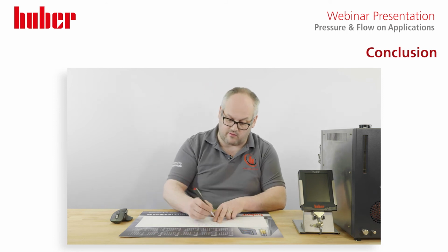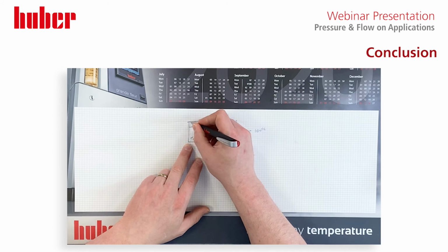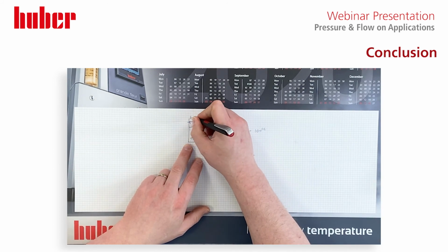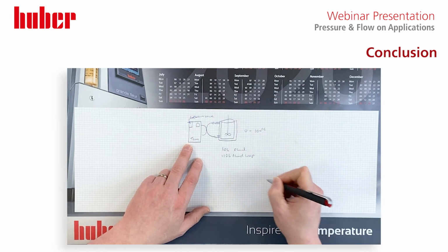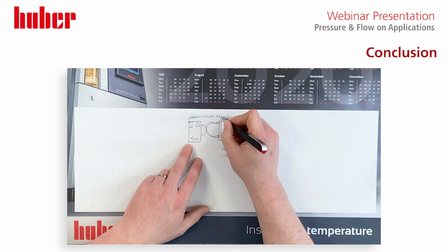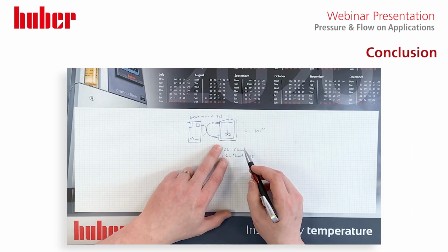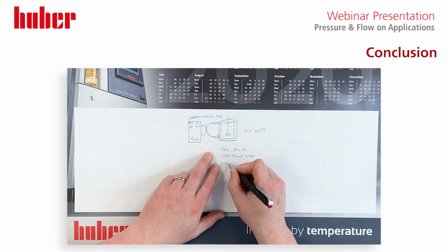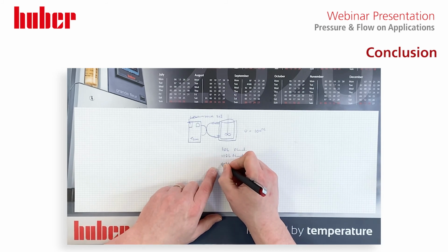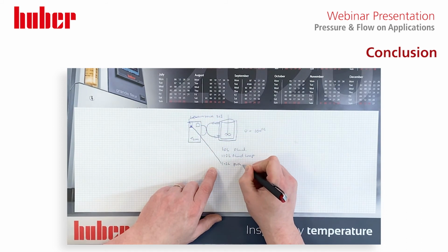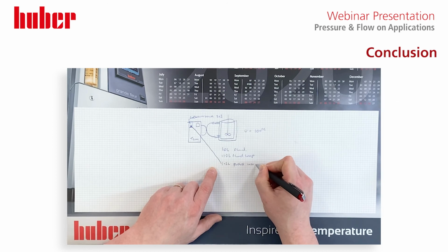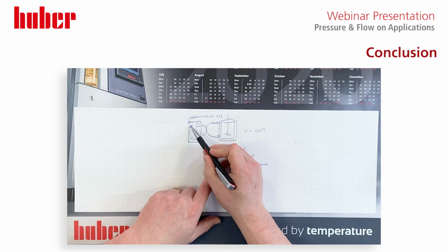However, in our Unistat system, normally in the top left-hand corner, we have what we call our expansion tank. And we normally run these at about 30% fill volume. The reason for that is our extra 1.2 litres in this system will actually push its way into the expansion tank, which is open to the atmosphere and thermally inert.